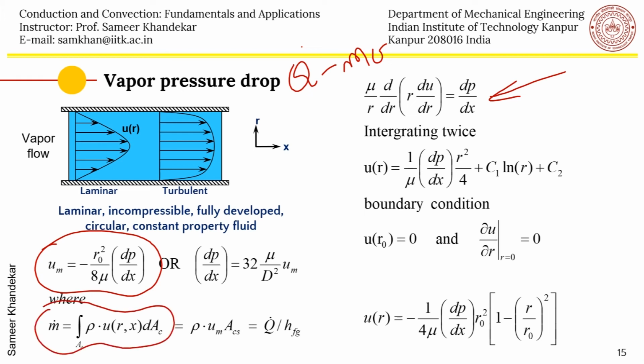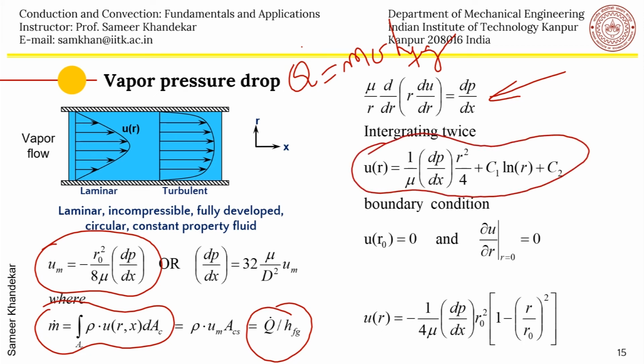We can assume no slip so that we get a good answer, which will be more or less correct also, because although there may be some slip, since the vapor is actually not touching the wall but the liquid saturated porous media. So once you know the velocity of the vapor, you can get the pressure drop because of the vapor.